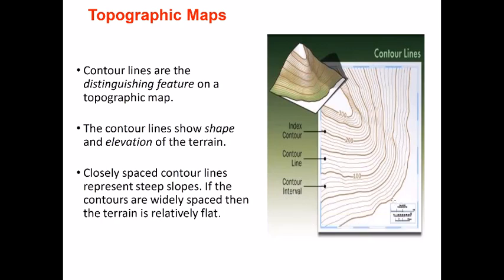And this elevation difference can be anything. It depends on what sort of project you are doing, how much the difference between the elevations should be, or what is the nature of the land. It depends on a lot of things. Basically, if I try to make contour lines for smaller contour intervals, the work that I have to do in the field will increase a lot. So that is why a lot of factors are kept in mind before deciding on the contour interval.